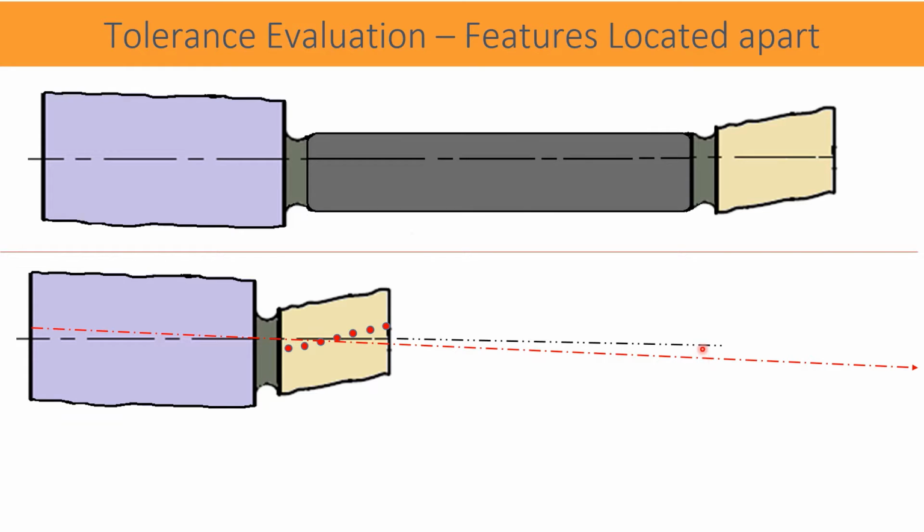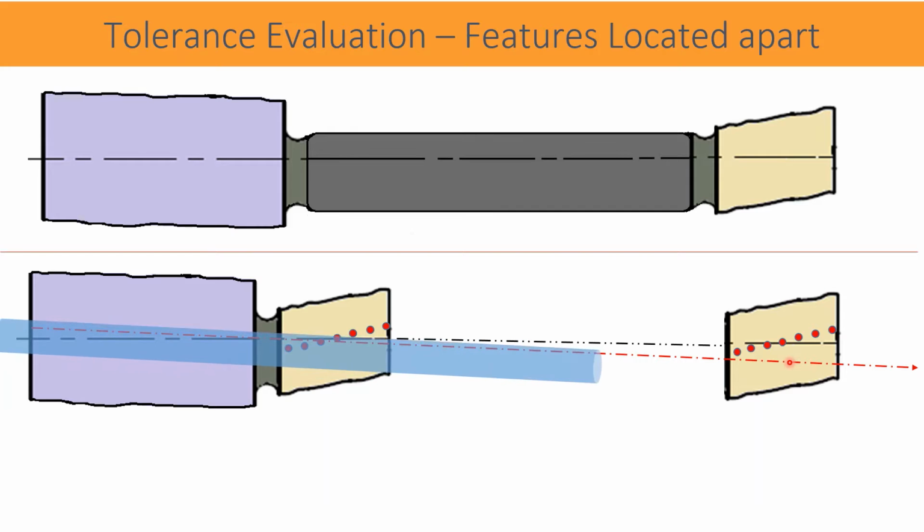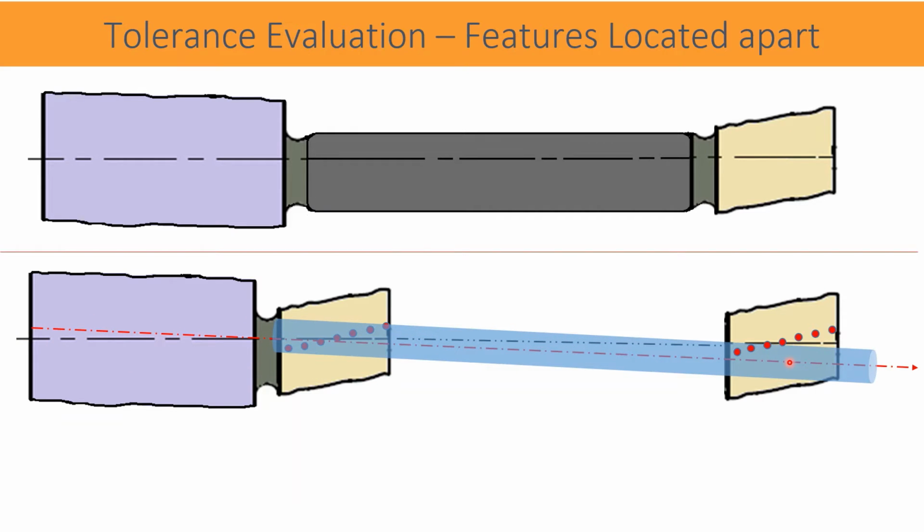This small inclination is enlarged when it reaches the tolerance cylinder. Around the datum axis, the same cylindrical tolerance zone is built. In this condition, concentricity calculated is out of tolerance value. The reason is simple: the tolerance cylinder is placed at the farthest distance and mathematical calculations produce more error.